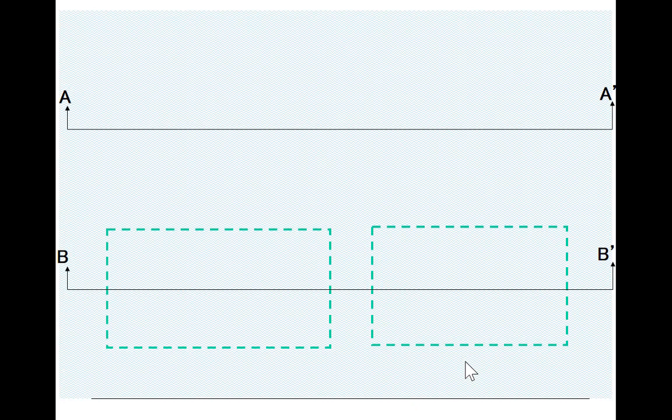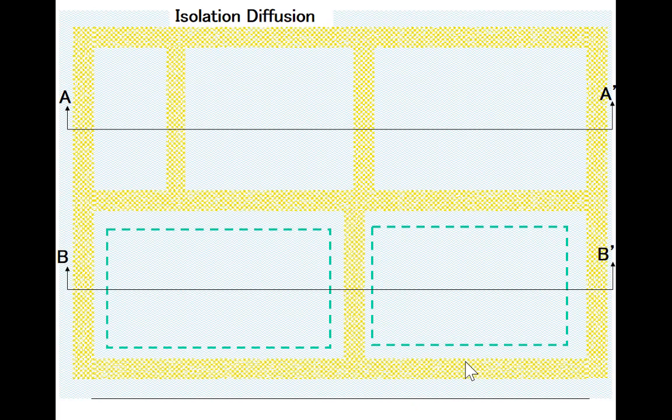Here's the top view. We put the isolation diffusion in. Remember, it started out all N-type now because we covered it with epitaxial layer. When we're done, we have these P-type diffusions all the way around these N-type regions. So now we see the electrical isolation is taking place. Any questions so far? We're about 40% done with the bipolar process flow. And all we put in so far is a buried collector and the isolation diffusion.